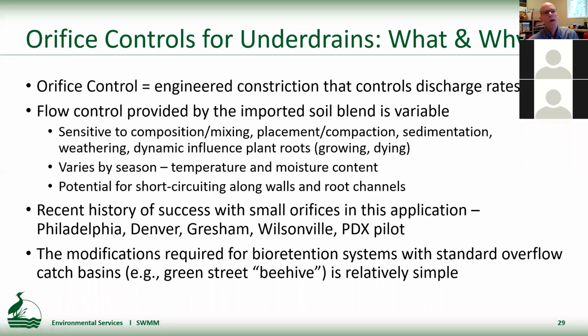Okay, so connected with the underdrains, we have a new orifice control requirement for many underdrain systems. I think a lot of you are professional designers and know what an orifice is. Anyway, it's an engineered construction that controls discharge rates, and we are among many jurisdictions that are beginning to require orifice controls to control discharge rates from these kinds of facilities.